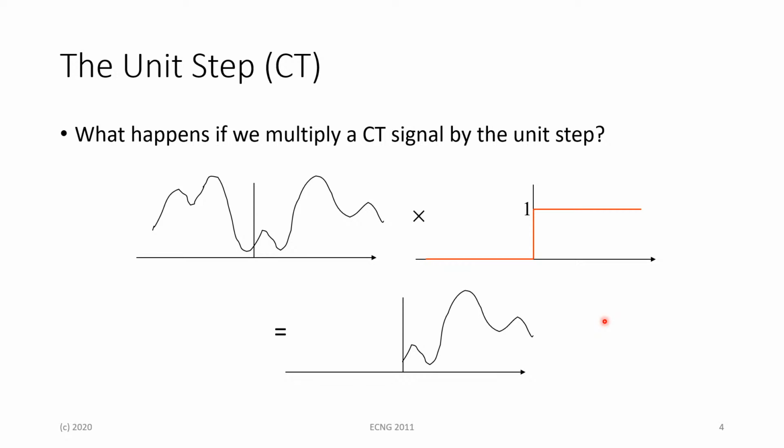Is a unit step signal like the clock signal from the FPGA boards? It is similar to it, but because you're dealing with real world components, it tends to be literally a very, very sharp ramp with a very high gradient factor. Because with real world electronics, there's a time for that change to actually occur. It's not instantaneous, but it gets very close to it, so to say.